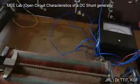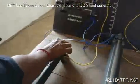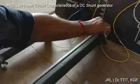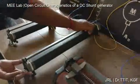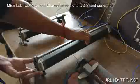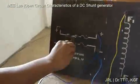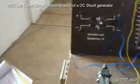Now it's the reverse procedure. Remove the switch, bring the 140 ohms to cut-in position, and then to cut-out position, and the 50 ohms to cut-in position. And then open the circuit.